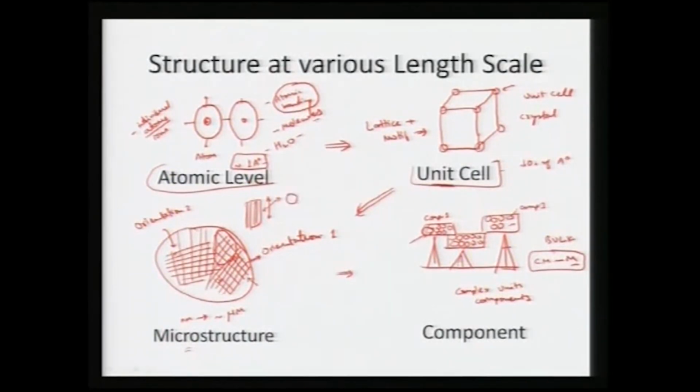If we tend to have a very random orientation of all of these grains, what we get is an average along all sides that will be the same, whether we take any direction the average will be the same. So, now what we get is an isotropic property.